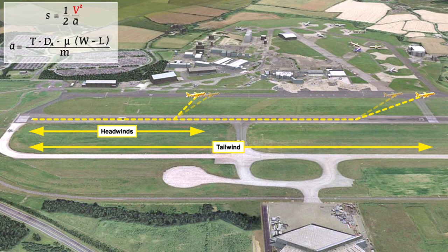When examining the effects that winds will have on takeoff performance, it is recommended that you do not use the actual wind that is given, just in case that when you do actually get airborne, the wind changes, and thus your takeoff distance changes. The safety recommendation is that the takeoff planning is carried out assuming a worse situation than the one which is forecast.